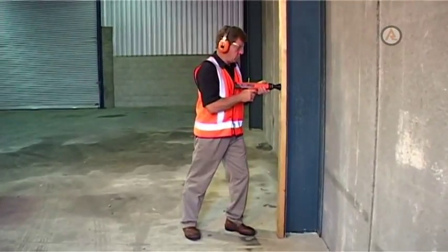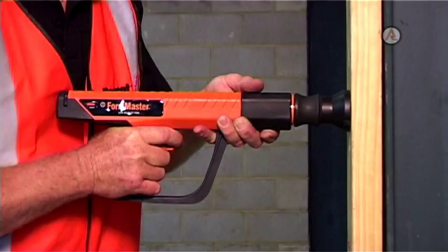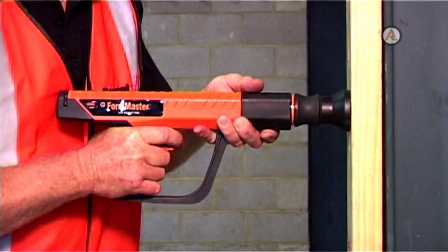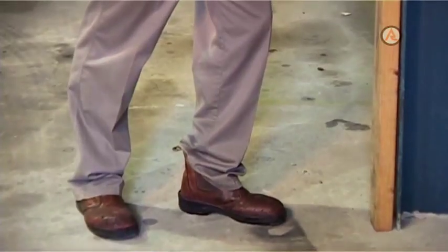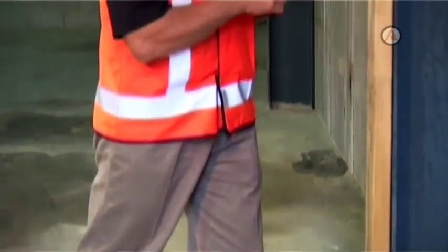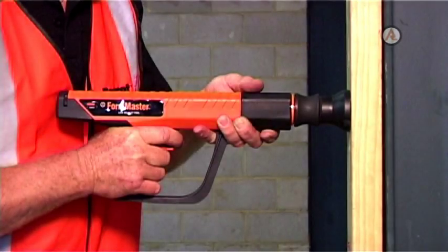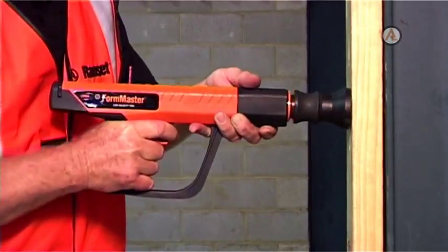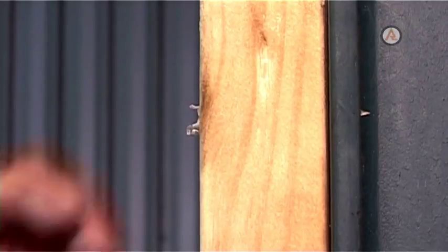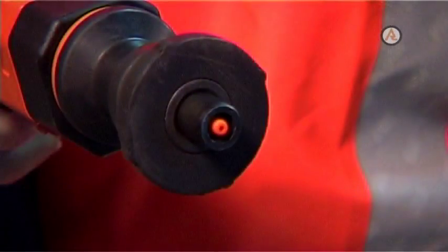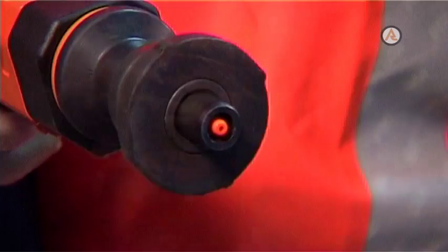Press the tool firmly against the work surface at a 90-degree angle. Keeping the tool perpendicular to the work surface reduces the possibility of ricochets. Hold the tool securely with a well-balanced stance so as to counteract any recoil of the tool. Make the firing call and pull the trigger. To further eliminate ricochets and deflections when the tool is fired, special spall shields or guards should be attached at the muzzle end of the tool when possible.